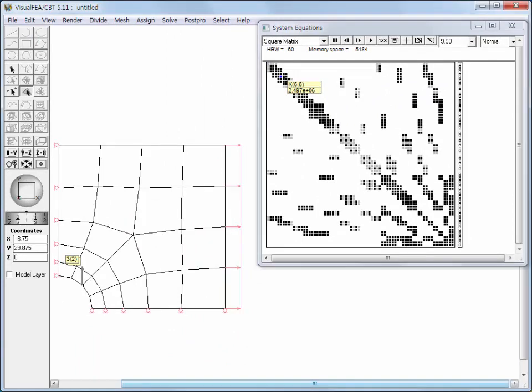At the same time, the degrees of freedom associated with the entry are indicated over the image of the model. A line arrow represents the direction of the degree of freedom. In the case of off-diagonal entries, 2 degrees of freedom are represented by 2 arrows. This display implies that the stiffness value is determined by the force displacement relationship of the 2 degrees of freedom.